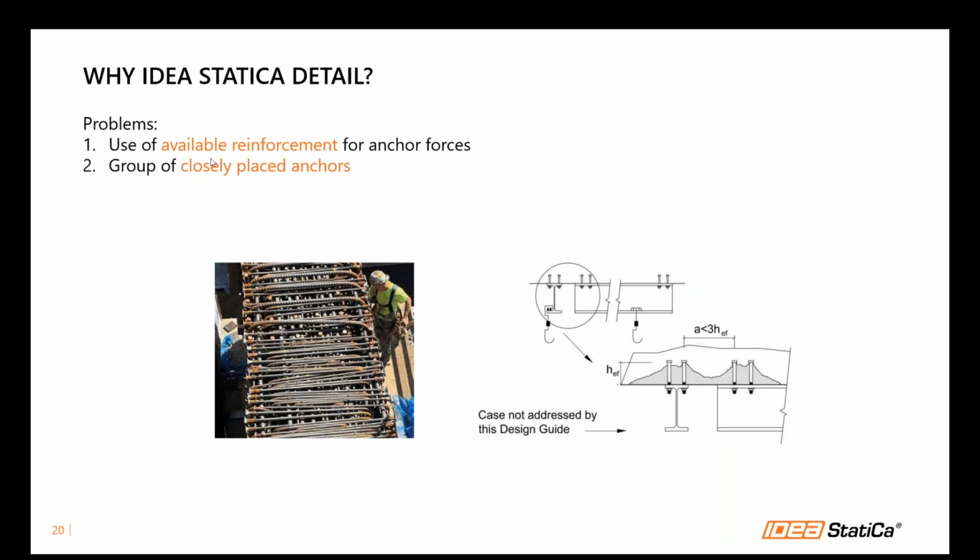So just to recap, basically the problem will be use of available reinforcement, how to figure out the forces, and then second one will be group of closely placed anchors. These scenarios are not well covered by the design code, but this is where IDEA StatiCa Detail can help you in your anchor design, because you can consider the reinforcement inside your anchor design.